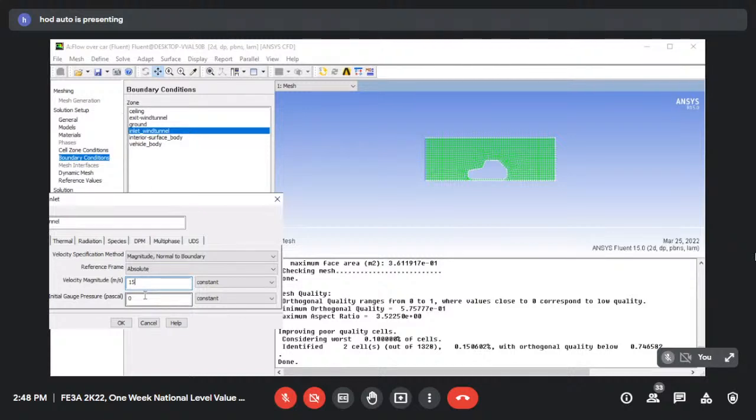So I am assuming that as per this 15 meters per second, rho is around 1.25, velocity is around 15, hydraulic diameter per unit width may not be more than around 0.1 meter, and divided by the value of mu, which is of the order of 10 to the power of minus 6. I am trying to take frontal area of the car of the order of 10 to the power of minus 3. Overall, when you multiply, I am expecting that it is less than around 2300. Or you can just put it on paper, we may get it.